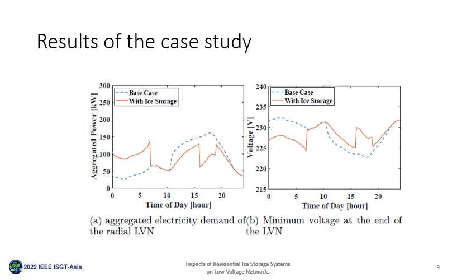And you can see with the ice storage, you have a higher electricity demand during nighttime because it's charging the ice tank essentially. But it is assumed that during that time you have maybe plenty of wind or plenty of electricity. During the peak period, however, in the afternoon, we can see that demand is much less compared to the base case, especially during the actual peak between 16 to 17. Between 16 to 19 in the afternoon, you can see the demand is significantly less.